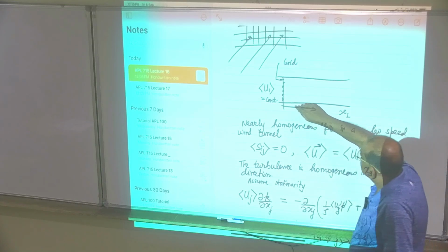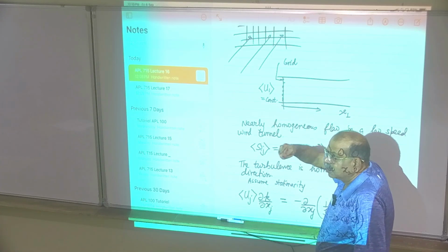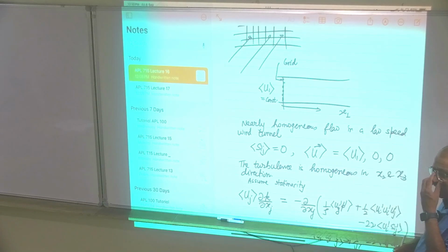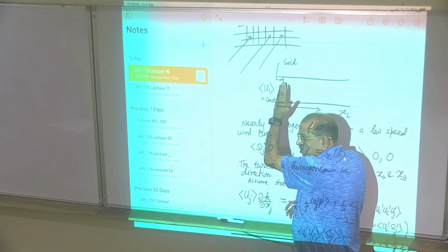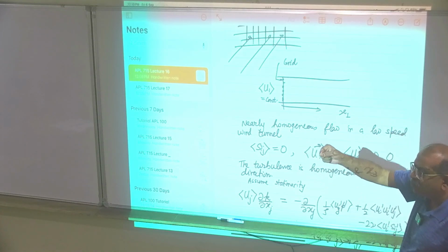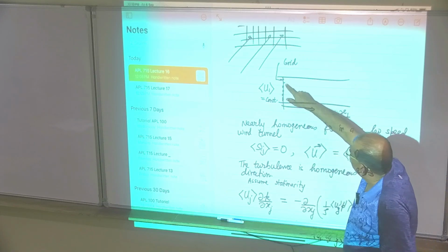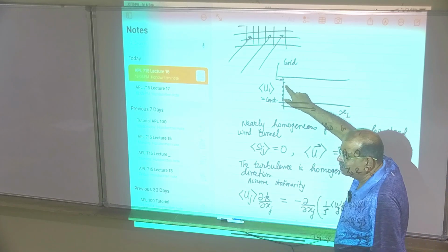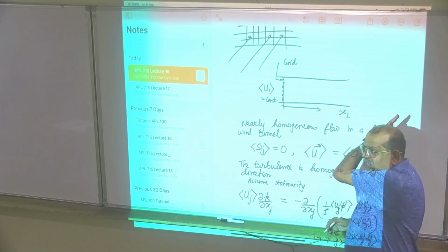But now, because of this grid, the grid will sort of decide the size of turbulence to start with, because if the flow is passing through this, then what you would expect is the eddies which will form, if their size is L as we have taken, that will be of the order of the size of M, the grid spacing, because everything is passing through this.